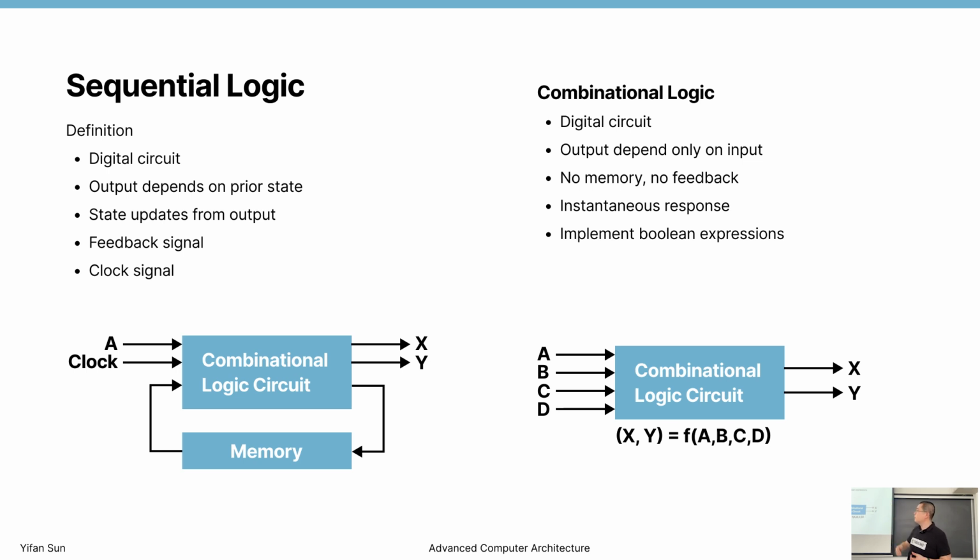That's why we say combinational logic generates output instantaneously. It doesn't generate the result in a moment, but it takes so short a time that we can almost ignore the execution time. Although eventually we'll see that the duration needed to calculate the result in a combinational logic circuit is a limiting factor for how fast our clocks can run.